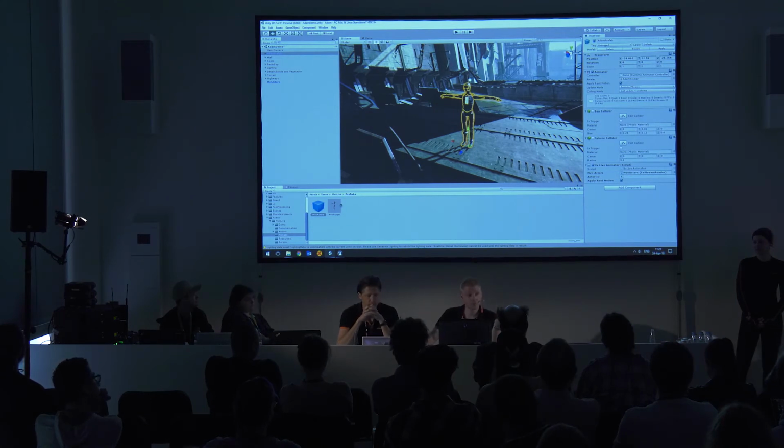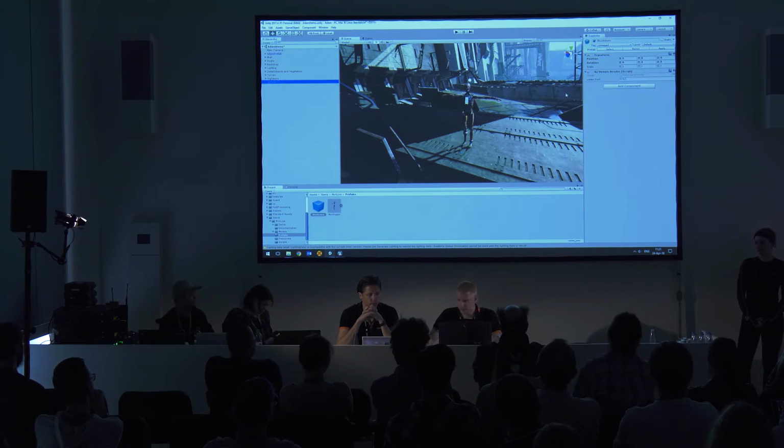Again, same as in MotionBuilder, we can stream up to 4 characters from one MVN instance. So you can change the actor IDs to the specific character you want to get the data from. What you can do in the MVN actors prefab is change the port that you're currently listening to.